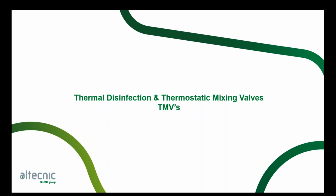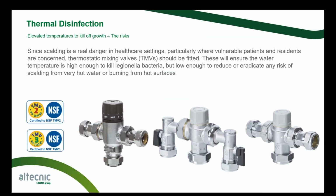Obviously, we are a manufacturer of TMVs, so we see different sides of the market. But since scalding is a real danger, especially in healthcare settings, particularly where vulnerable patients and residents are concerned, thermostatic mixing valves, or TMVs, should be fitted. These will ensure that water temperature is high enough to kill Legionella bacteria, but low enough to reduce or eradicate any risk of scalding from very hot water or burning from hot surfaces.